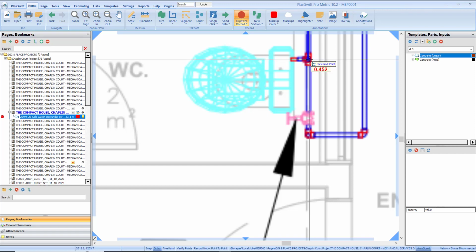This WC is the S-trap type of WC. Remember, we have the P-trap and then we have the S-trap type of WC. Most times your S-trap type of WC is mounted on the ground floor, and we are on the ground floor, so majorly there is a pan connector from these.